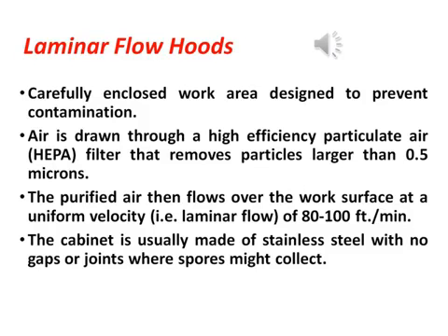Laminar flow hood. A carefully enclosed work area designed to prevent contamination. Air is drawn through a high efficiency particulate air filter, or HEPA filter, that removes particles larger than 0.5 micron. The purified air then flows over the work surface at a uniform velocity. The cabinet is usually made of stainless steel with no gaps or joints where spores might collect.